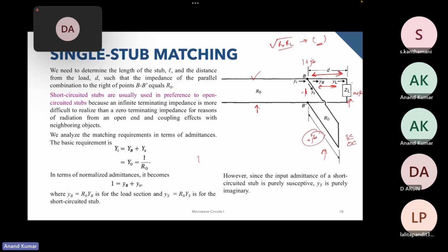such that at this particular point the impedance that we are looking at is 1. When I'm saying 1, it is basically the normalized form. So this capital ZL can be written as small ZL. Small ZL can be of A plus JB form, and then while translating from here to here, this becomes 1 plus JB form, and this minus JB subtracts this part, and we get 1 over here. So this is the idea of using a single stub.